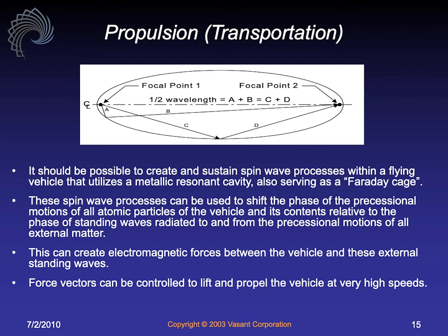That induced current flow causes a counter EMF, and once it gets back to the source that caused it, normally, according to Lenz's law, it would provide a counter force, and that's how energy gets converted in motors and generators, from the force applied to electrical energy output. But if you have very, very high frequency feedback, it ends up coming back and applying a force that reinforces the initial signal rather than counteracting it.